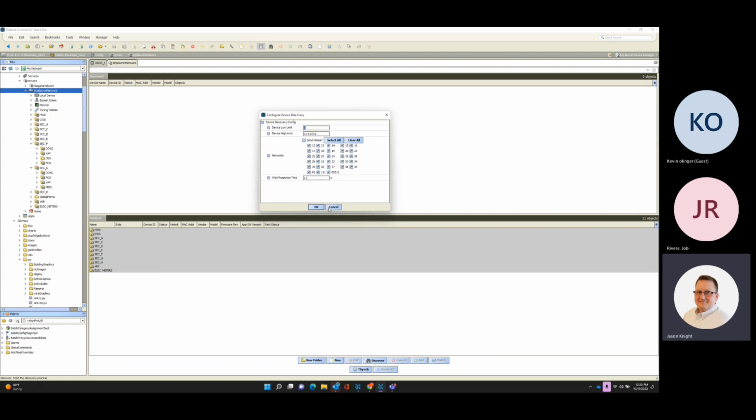Now, the reason that that's important is because all your other equipment, let's say you go to Sector G, second floor, you open one of our control panels and you see one of the BACnet routers sitting there flashing at you. When you troubleshoot, that router has a direct line, a Cat6 cable, pulled from the router over to the adjacent IDF room. And you're familiar with this, Kevin. It goes specifically to a port on that switch. Port 46 is this router. Port 47 is that router. Port 44 is this router. And that's how your IT department manages that.